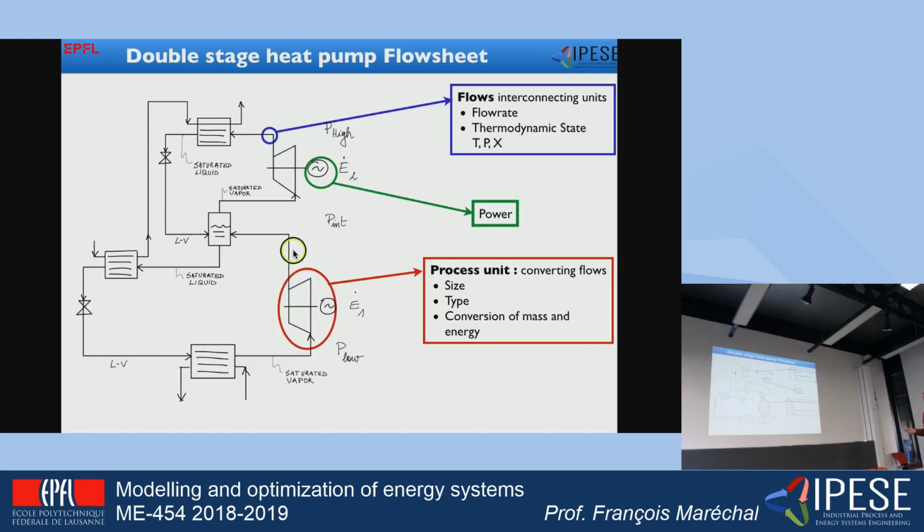So here it's a compressed state, vapor state, goes into a liquid vapor separator here, is going to be separated into a gas flow, which is here, that is going to be again compressed in another compressor here, come to a heat exchanger where the fluid is going to be condensed.